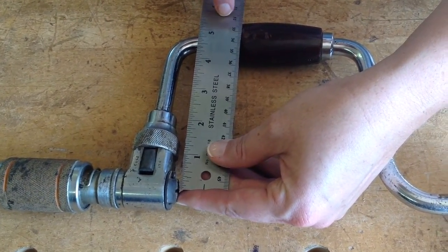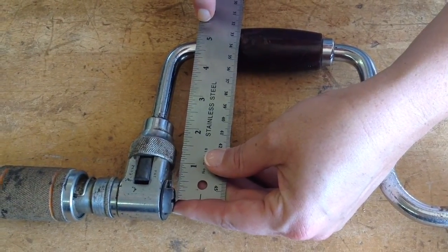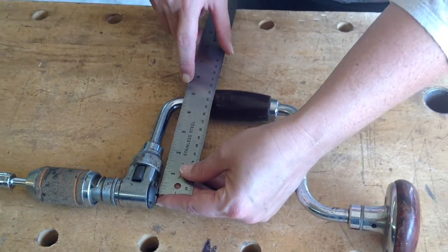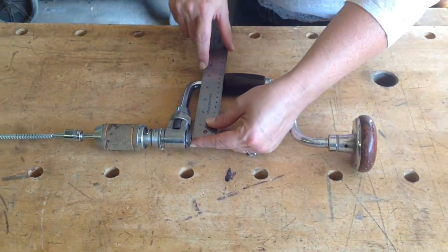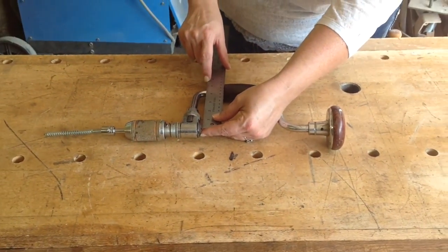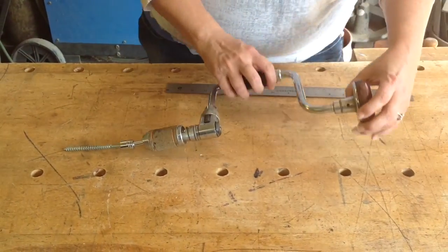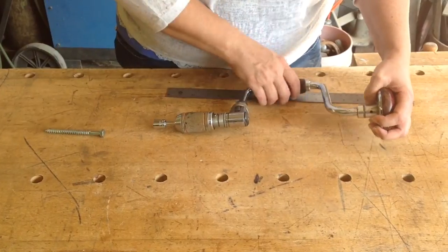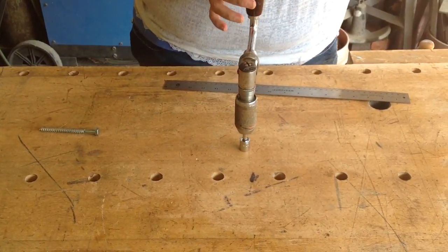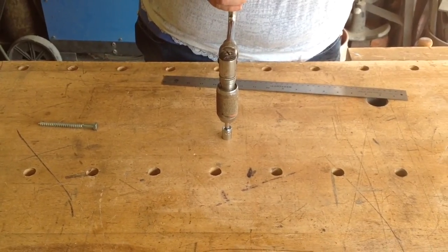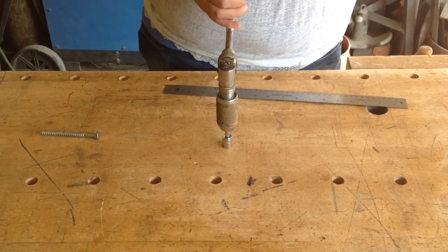The outside of the handle is about right here. So that is 5.5 inches. So the radius is going to be 5.5 inches. So to find the circumference, which is the actual distance that my effort is actually traveling, okay, so the effort, if I start here, go all the way around, that is the circumference. And that would be my distance effort.